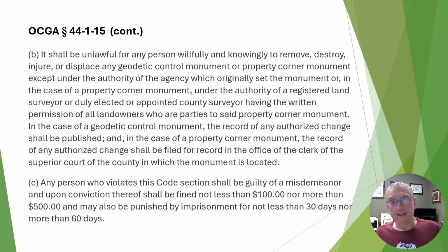And I guess it would be a good idea, perhaps a requirement, to record something that says the 2-inch pipe that used to sit on the bank of Podunk Road is now a capped 5/8 rebar because they cut the bank down 15 feet. That's a gray area, but that's what the law says about it. The main thing is it's unlawful to pull up corners. And if the people that were around are pulling up corners, sometimes you have to remind them that you're breaking the law. And this paragraph C here sums it up.